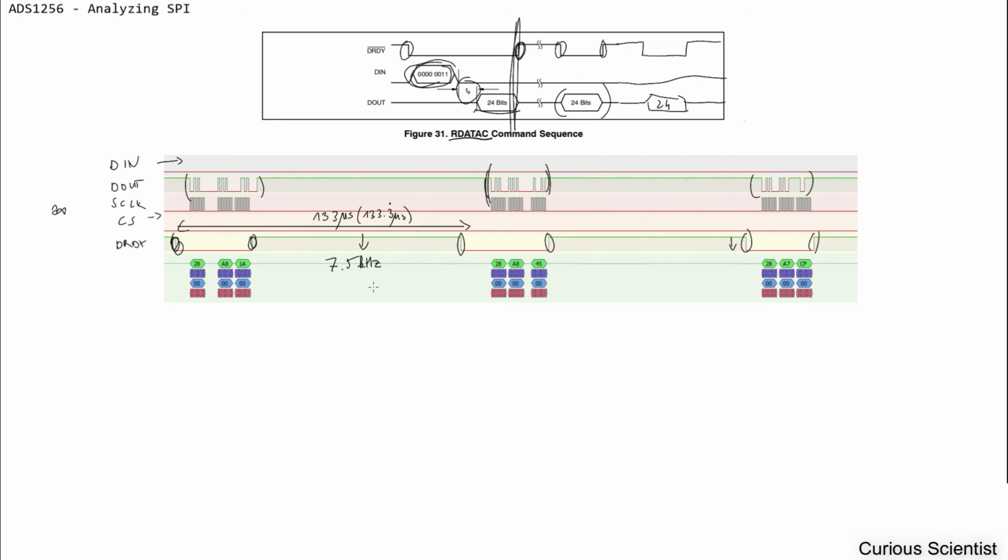But if I have to send data more often and I have to cycle through the registers manually, then there is a slight delay as compared to the values in the data sheet. So here I just wanted to demonstrate that this automatic output of the data works very well, and also the timings between two data ready are according to the data sheet. So this was all basically.